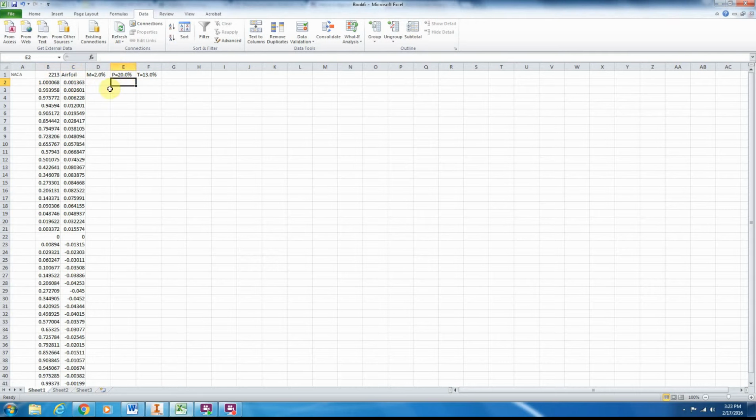So, next step. If I brought this into Inventor, I'd end up with a chord length of 1 inch. I'd like to scale this up by a factor of 4, so I have a chord length of 4 inches. So I'm going to define a scale factor, and I'd like that to be defined by the number 4. Now what I need to do is I need to multiply each point by that scale factor to begin scaling it up. So I'll start off with an equal sign.